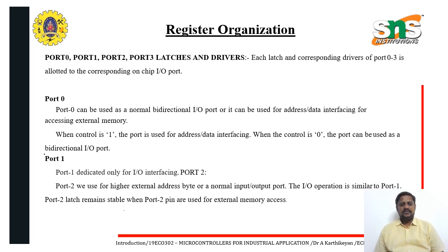Especially port 0 can be used as a normal bidirectional input output port, that is both input and output. Bidirectional means it can communicate in both directions at a time. It can also be used for address or data interfacing, for accessing external memory. That is the main usage of port 0.